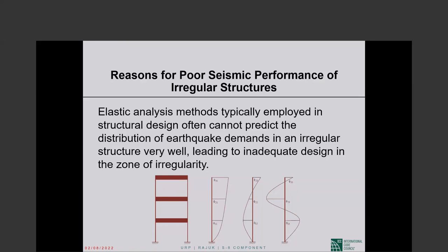The building with the two open faces and two back faces with walls that I mentioned: when the shear wall is damaged, the structural behavior is not regular anymore. So how would you find out from elastic analysis what is happening subsequently to the shear walls and, more importantly, to the columns? You cannot. There is no way you can figure out the actual force distribution after the behavior of the structure has become inelastic.